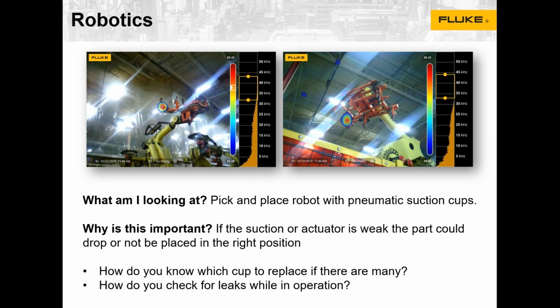Here's another one where I was involved in, can kind of help unpack the story here. So yeah. This is a pick and place robot. These types of robots, or this type of automation, looks a lot different depending on the process, or depending on the industry. But this is a pretty large scale pick and place robot, and essentially what you've got there is a robotic arm that moves around, and then the head drops down onto a particular component, and then it uses suction or vacuums to pick something up, move it to another part of the production line or the production process, and set it back down.